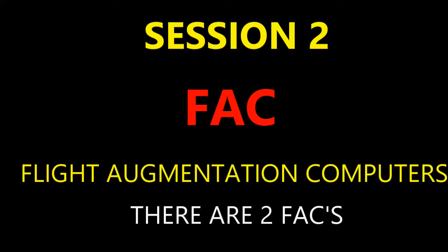If you have the FAC push button released out, the FAC is disengaged, and then you're going to have that white off light show up. Okay, just a note here. After a power up, which is your 30-second test, it's like booting up. The FAC cannot be engaged during that time. It's just like booting up your computer. How many things can you start operating? Well, you've got to wait till it warms up. So there's a power up test it's got to go through with the aircraft, and then you're able to engage that FAC. So you have that.